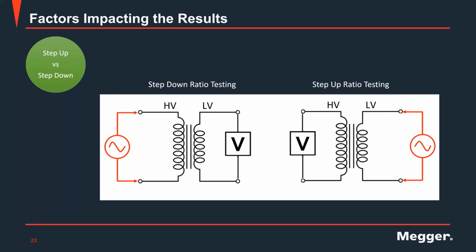So it's really important to highlight that if you want to do a step up, you need to have an instrument that is capable of doing it, or you want to know and to limit that voltage on the high side to safe levels both for the instrument and more importantly to the individuals involved in the test. But why step up? And obviously stepping up the voltage will improve the accuracy of the test, but why does stepping up the test voltage yield better accuracy, right?